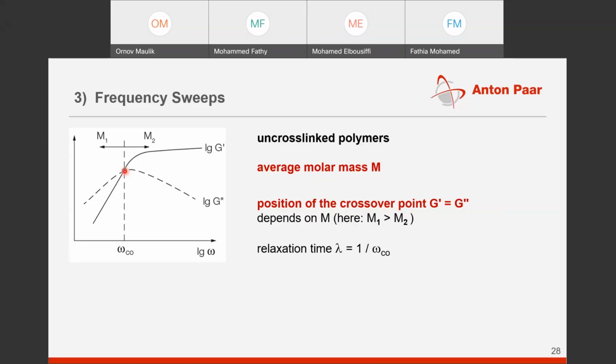The reason for that was mainly that we have given an improper relaxation time, or our die length is not big enough. This type of information is very crucial in designing the die length and in determining how much time at least that melt has to be in the extruder in order to avoid these types of defects.